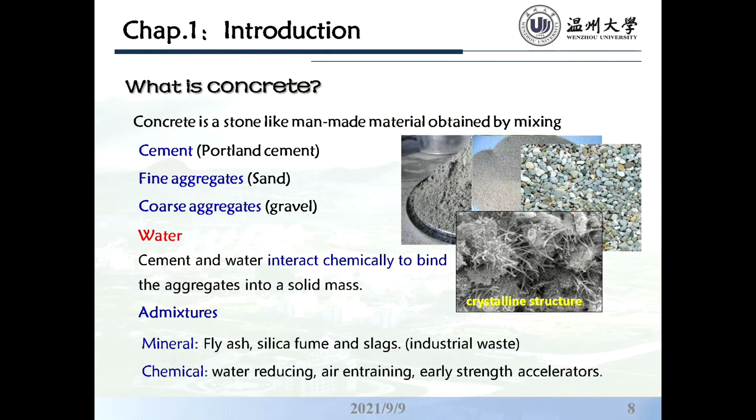And for chemical admixtures like water reducing or early strength agents, because we know the concrete at first is in a fluid state, we add these things to accelerate the hydration process, to quickly let the concrete gain strength so that it can work. That's the purpose of the chemicals that we add in the concrete.